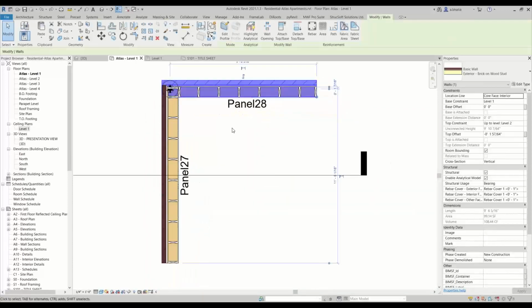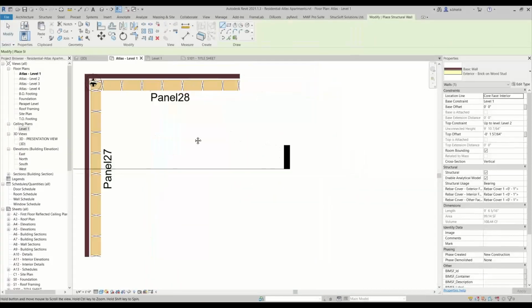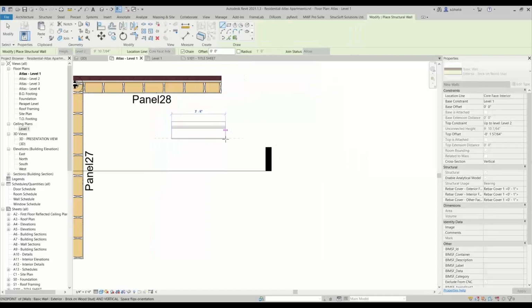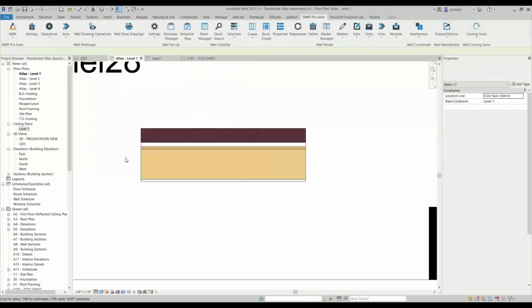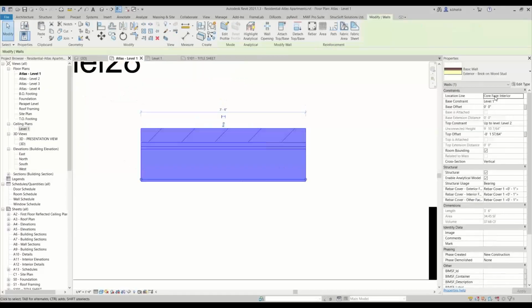Yes, so that's why when we were trying to adjust the wall structure or moving the substrate out of the core layer, basically what we did, the first step, was make sure that the location line is set up exactly where we want our walls to be aligned to. So pick a line, pick a face of the wall where you know that that face cannot change.